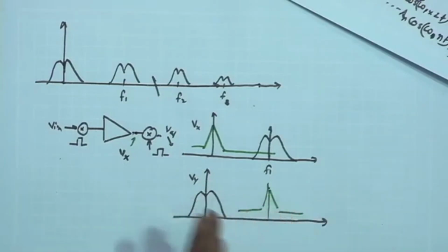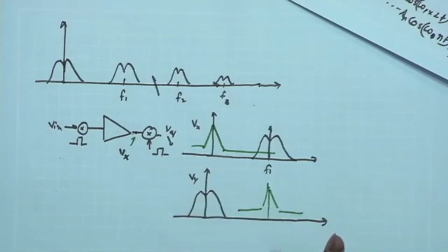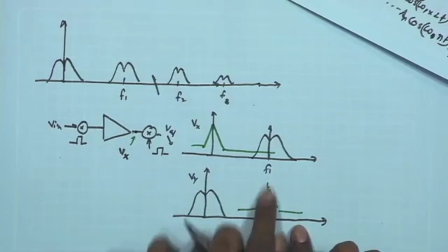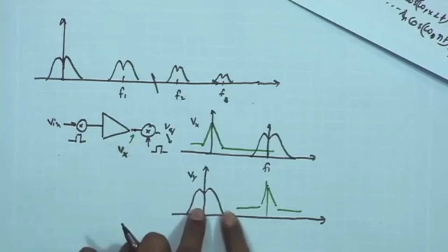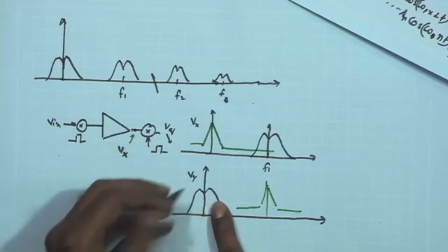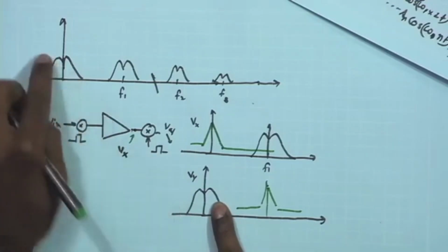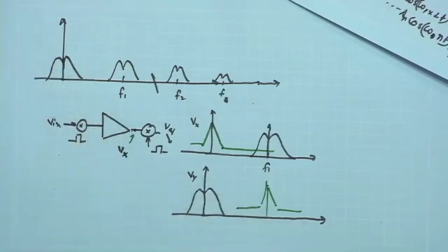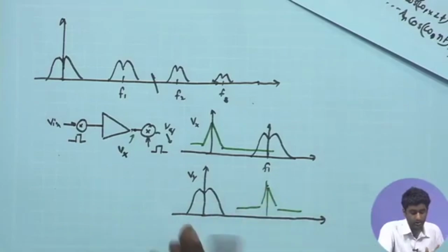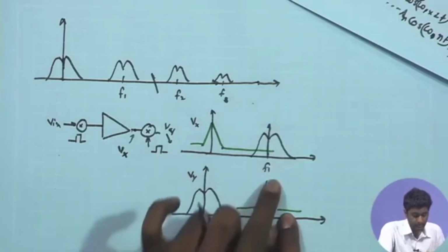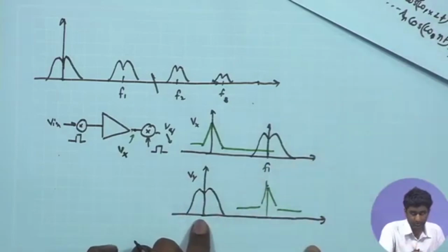So, basically I have been able to separate out my 1/f noise component from the desired frequency component, and hence mitigate the effect of this sharply increasing 1/f noise component at the low frequency, which was interfering with my data. Now, if I assume that the signal has been sufficiently magnified, so you also have this magnitude which is A times the input magnitude, which is going to be significantly higher, and therefore the 1/f noise or the thermal noise of the subsequent stages may not be so significant as compared to the signal over here.